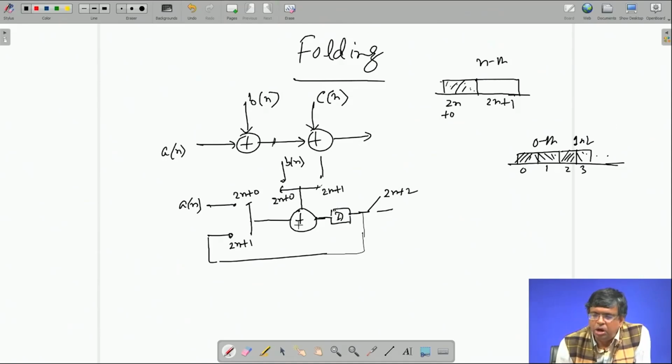So, you see I used only one adder. So, adder complexity has gone down. Of course, I am using switches which are muxes, but here 2 adders were replaced by 1 adder. I could have had 100 adders, still I could have used only 1 adder to replace all of them. Clock would have gone up by 100 times, but the number of adders would have gone down by 100. And I would have used the signals in a time division multiplex manner.